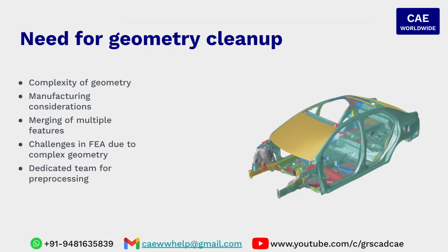Geometry imperfection can also come because of multiple features coming at one place, like chamfer, fillet and draft, and some cutout features merging together and creating complex corners. As you can see on the right hand side, for example the car geometry, these are going to create challenges which the finite element analysis engineer has to deal with.